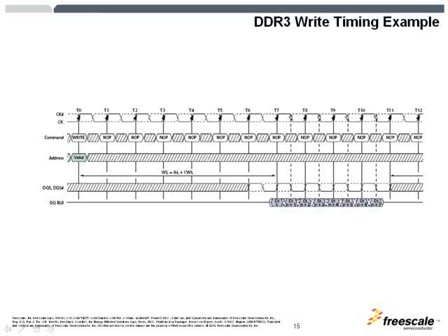The second thing that you can notice is that the preamble, the signal that is sent before the strobes are center aligned for the data, goes about half a cycle high and then half a cycle low.